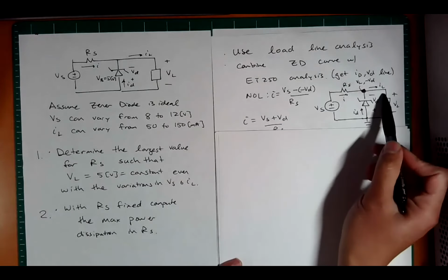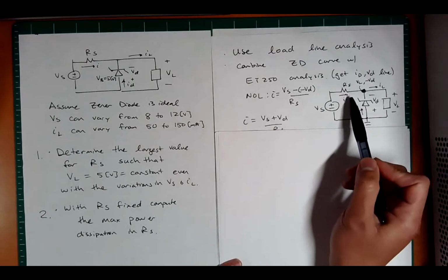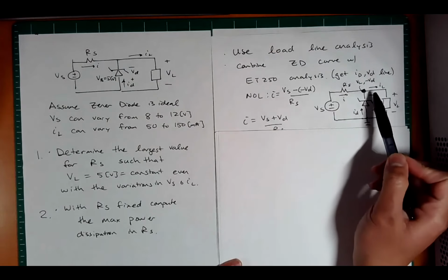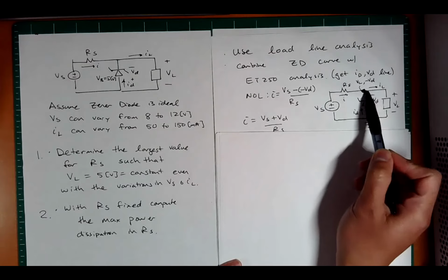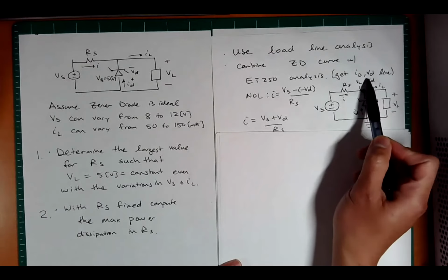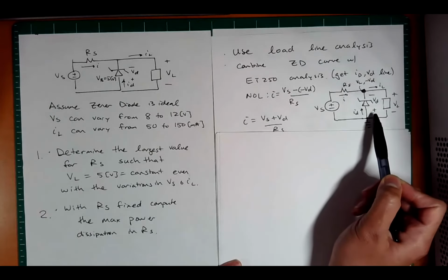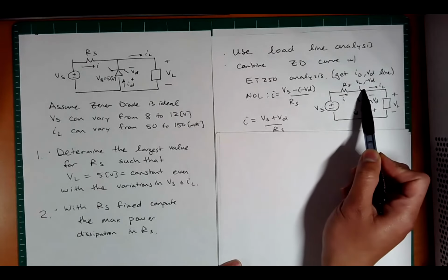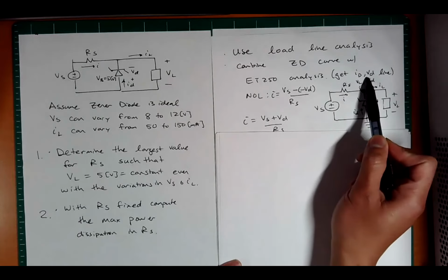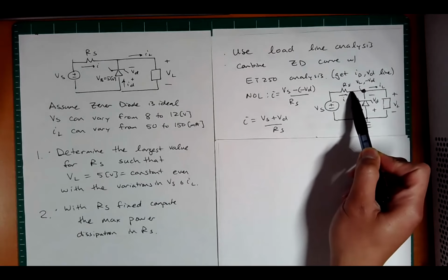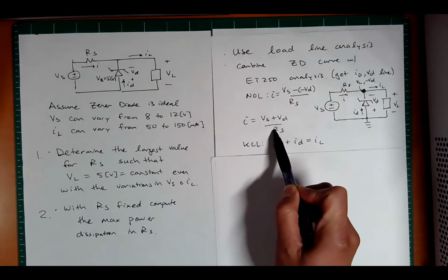Okay, so let's go back to our little system here. I just basically redrew this, right? And so what's going on? I have nodal Ohm's law. Now be very careful. Look at this node voltage. I put a little ground here. The node voltage at this point is either VL or it's negative VD, okay, because of the way this is drawn here. So I can do an Ohm's law here. Current equals the node voltage Vs minus negative Vd over Rs, no problem. Or I is equal to Vs plus Vd over Rs, no problem there.